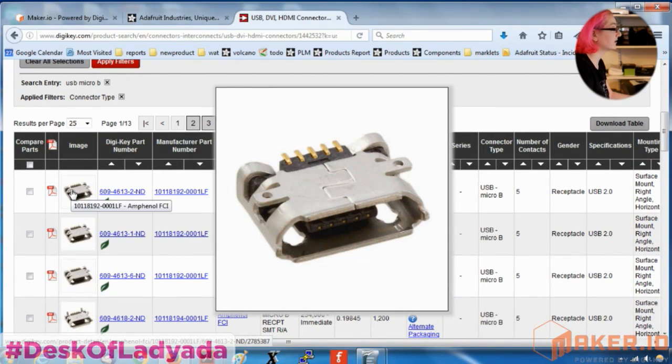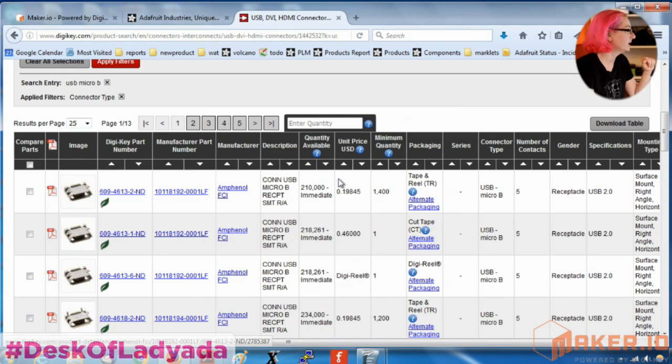So this is an SMT only one. You can see the pads that come out are not through hole style. They sit flat on the PCB. If you have an enclosure or really huge pads and vias, you can get pretty good mechanical reliability. But I find that people will rip them off. Still, these are basically 20 cents.